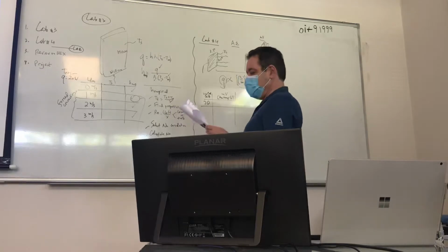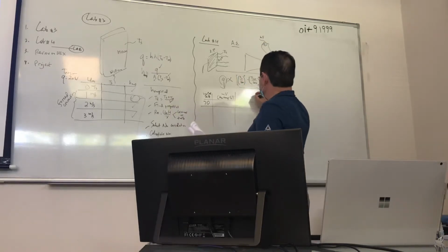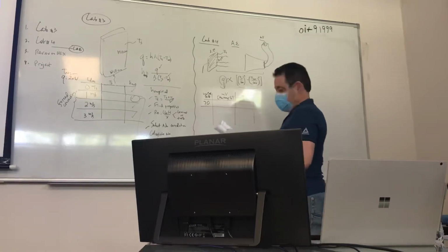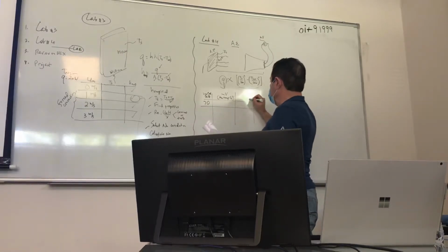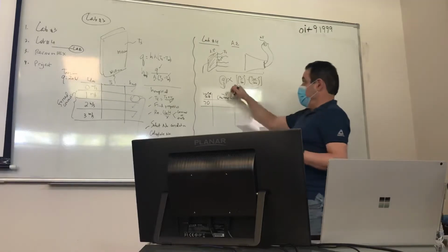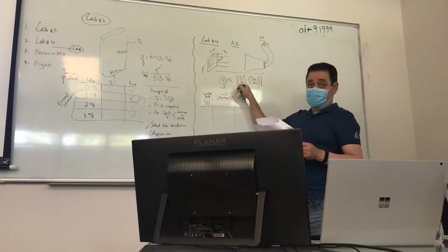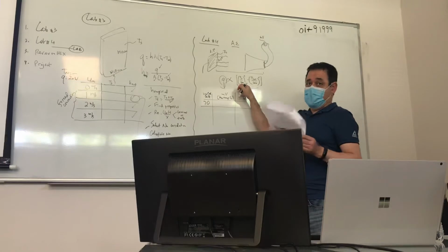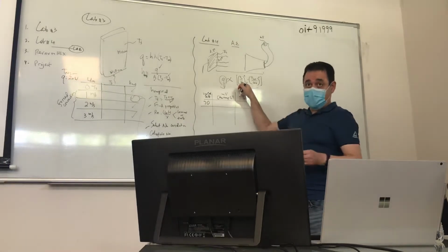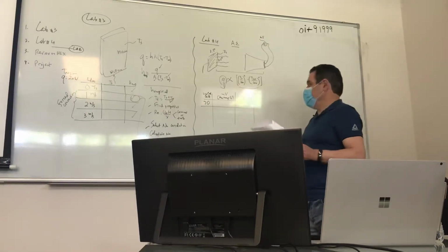We're going to read that, and then we're going to be reading what? T sub S, right? T sub S in degrees F. Remember when you use this equation, is this temperature in degrees F? It better be replaced by degrees Rankine, okay.